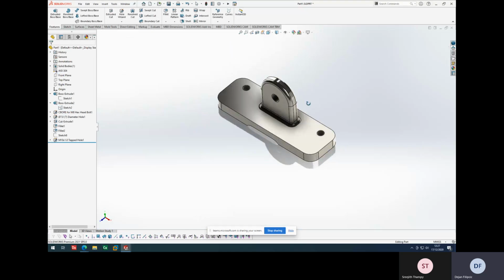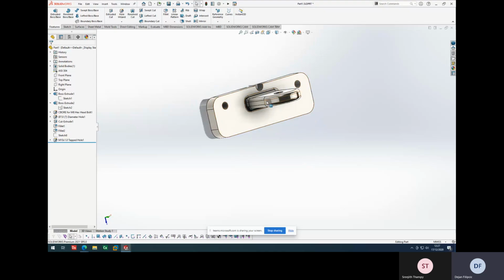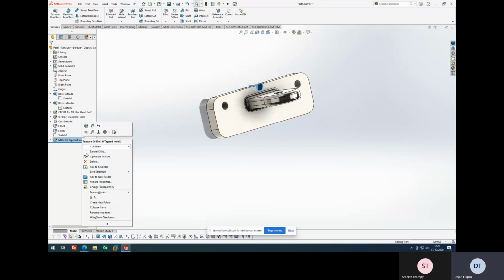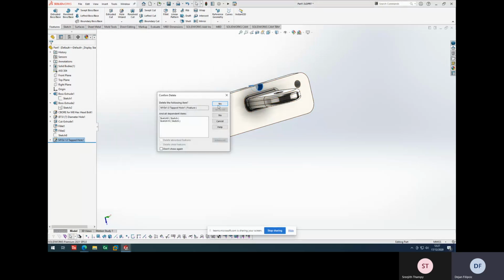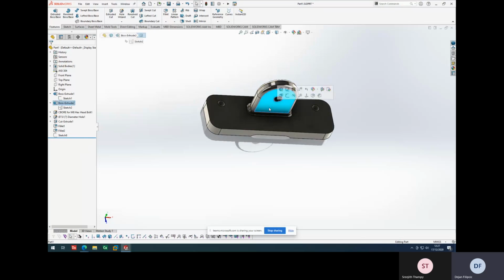Can you now make the extrusion go in both sides of the sketch plane? This thread was associated with a line that I have created from this, so there is a change. That's okay. So the extrusion for this part that protrudes out, can you make it midway, half in? Yes, for sure. Let me show how. I go back to the extrusion and edit the feature.